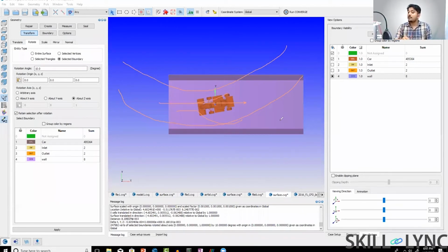Mayank, do we change boundary conditions when we change the yaw angle? That's a great question. The answer is yes. Why? Because when you're turning, you are most likely going a bit slow, right? Which means your inflow conditions can no longer be 80 km/h. It has to be smaller. How small? Again, that depends upon the average turn. And that is where you need baseline data.